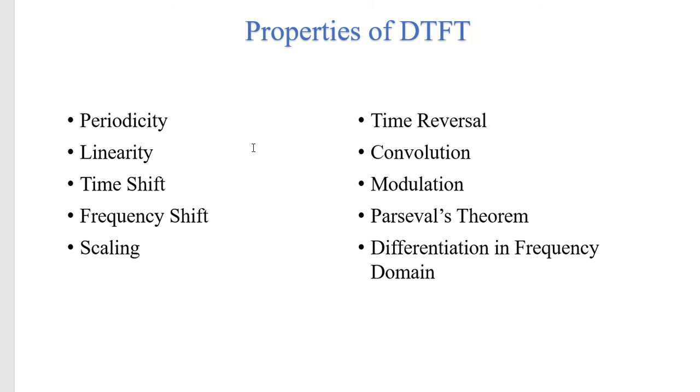In this, the same thing will happen. Whenever you take two signals and multiply them together and name it one signal, and then when you take the discrete time Fourier transform of your signal, you will get the convolution, not of the original two time signals, but of the DTFT transforms of the original two time signals, and the whole thing will get divided by 2 pi, which is basically the whole area. So that is the modulation property for you.